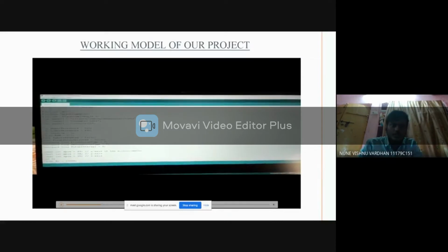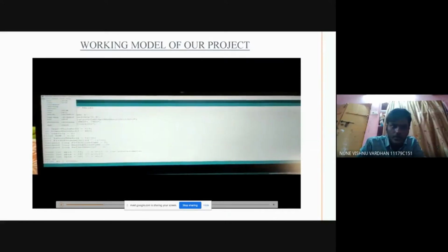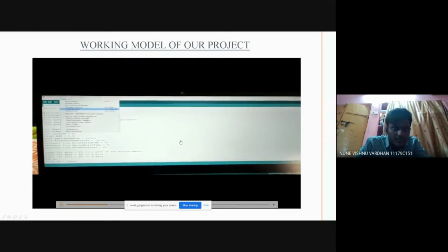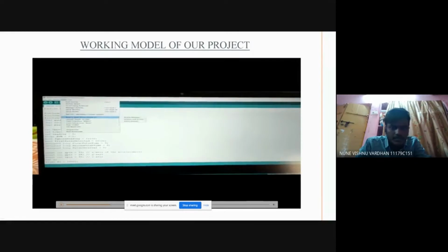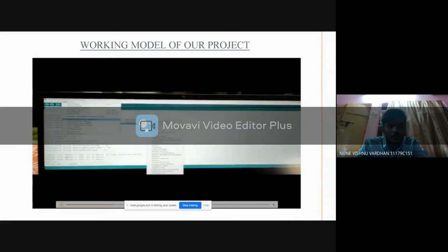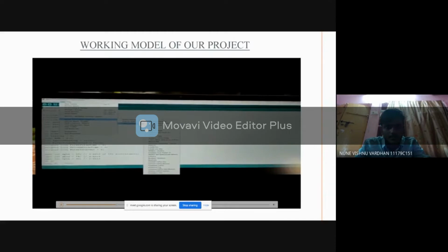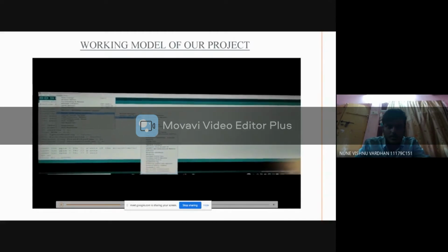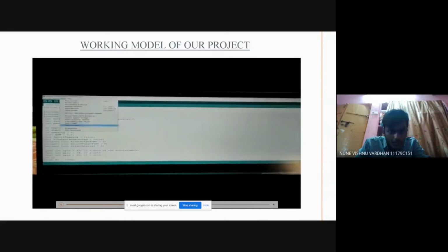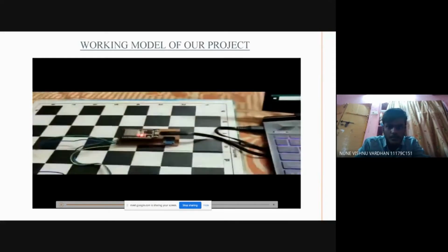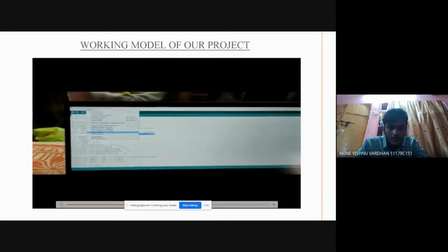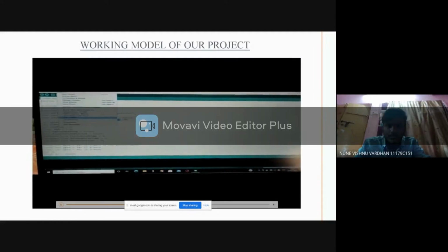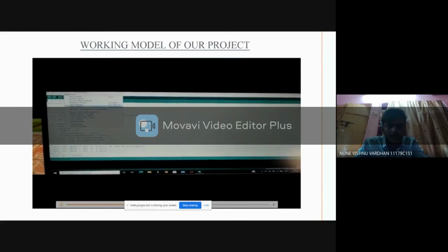Mainly the working of the ESP32 depends upon the given code or the given conditions in it. These are some of the interfaces that will be provided. There are separate Arduino boards, so we have to select the board manager and select the particular Arduino or ESP32 dev kit board first of all. We connected the hardware part using the USB cable to the laptop for dumping the code initially, and the power supply is also simultaneously given to the hardware circuit.